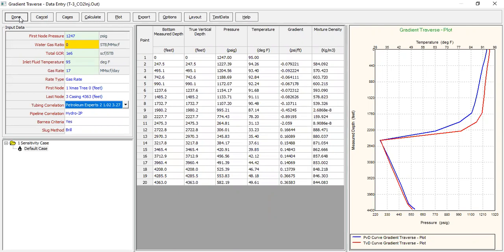That's another case, and the other cases are the maximum injection temperature and then the maximum gas rate to be injected. Okay, so this is the base case. Then I will run in total 4 cases. Then the second one is I will try to do temperature sensitivity and then rate sensitivity and then pressure sensitivity.